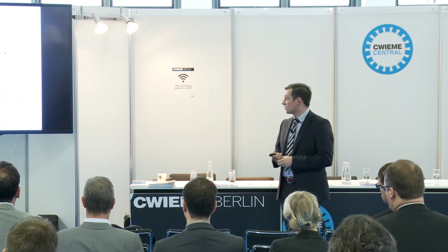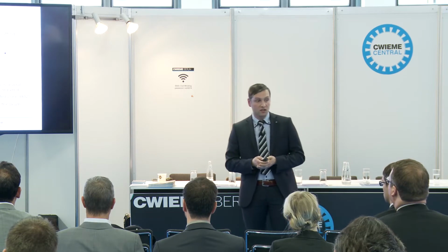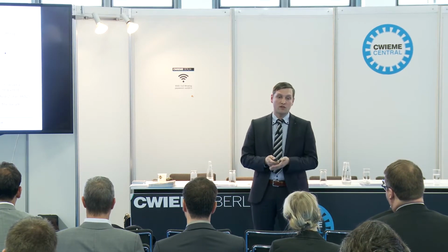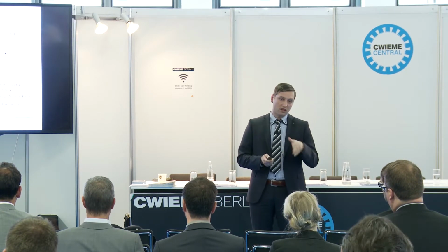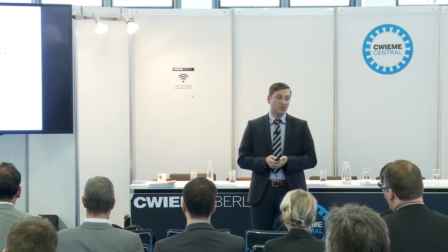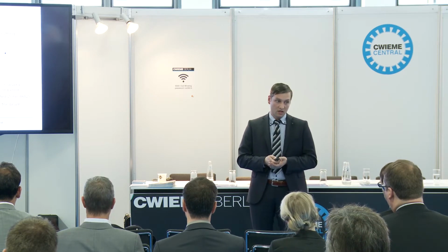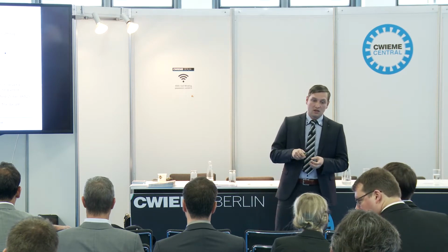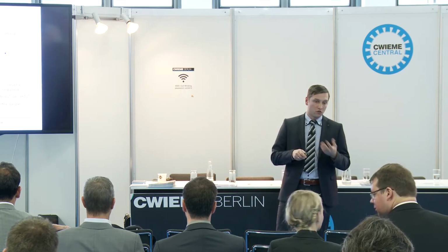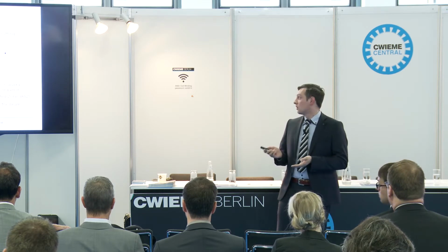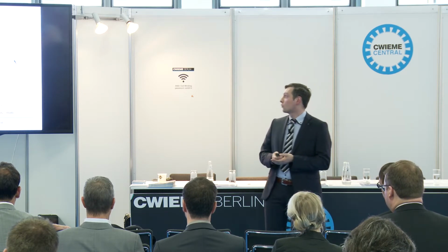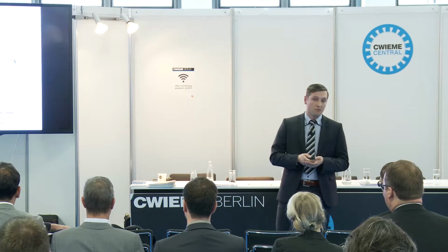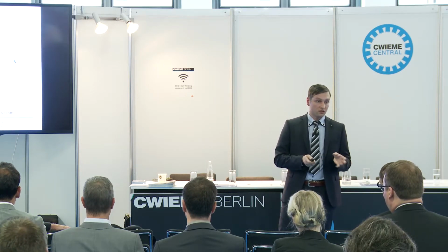The cutting is actually done with a scanner that deflects the laser beam very fast. For one cycle, you can reach cutting speeds up to 600 meters per minute. And in order to analyze cycle times, we did a cycle time comparison with the laser fusion cutting.